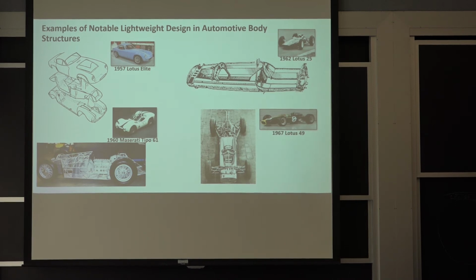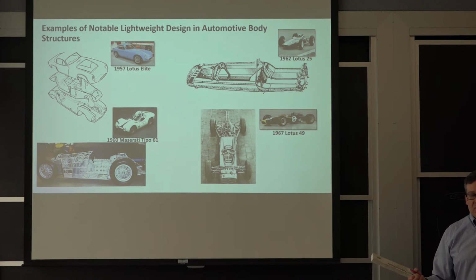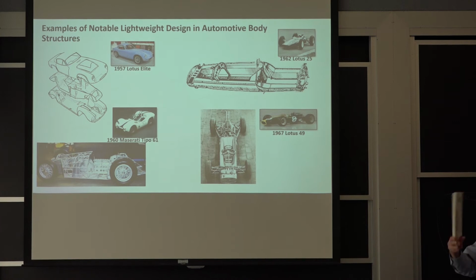A monocoque structure means that the outer skins of the structure become the stressed panels. So this is very different than what you'd call a space frame. A steel bicycle frame is a space frame. You have discrete tubes that are loaded in tension, compression or torsion. Well, no, I guess a true space frame is only tension or compression. But the point is that if you have a race car that's made out of a tube structure, the body panel, the outer surface, is just cosmetic. It keeps the wind and the water out. That is the opposite of a monocoque structure.